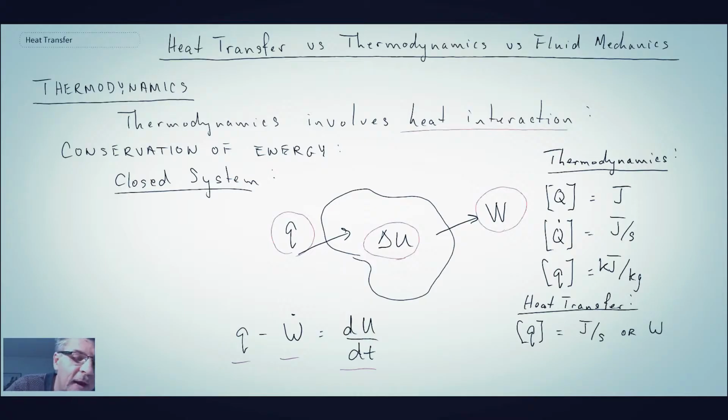And you notice by comparing these two together, they're different, so just don't get confused by that. In heat transfer, little q denotes joules per second. And that's why this version of the first law might look a little funny or strange if you've just taken a course in thermodynamics. But that would be how heat transfer is involved in a closed system.